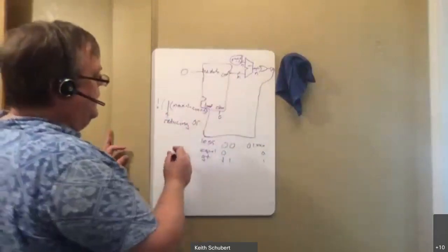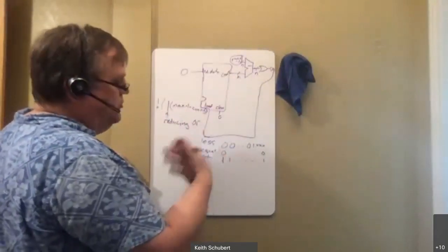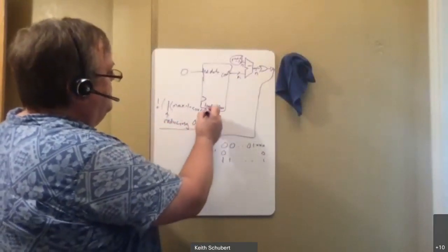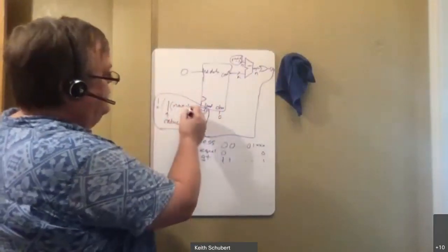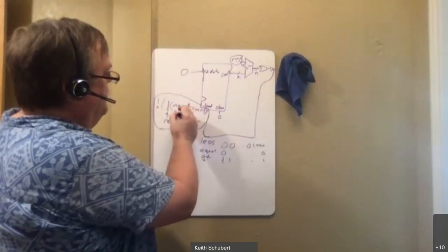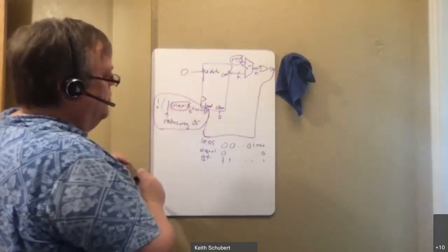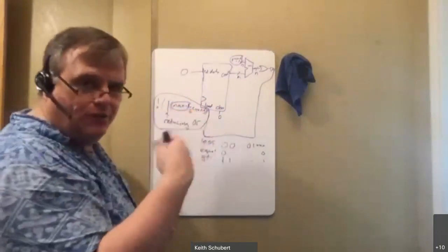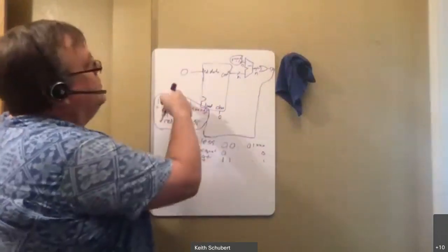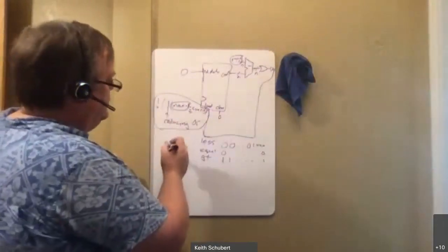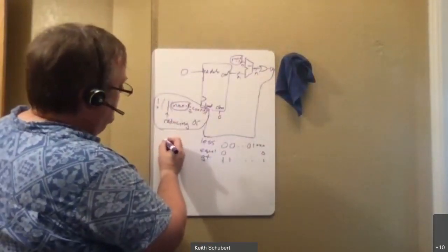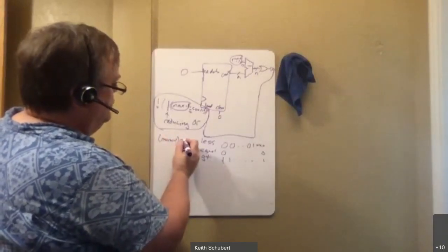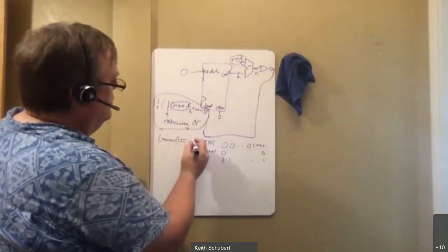The other way, remember, is doing a comparator. This is fairly simple to build, and it at least takes advantage of this subtractor. I'm assuming max minus 1, you just store that number. So you don't actually do that minus 1 subtraction. You've done it in advance. So this is using the subtraction version. The comparator is even easier to write. Max minus 1, and we just use the double equal.